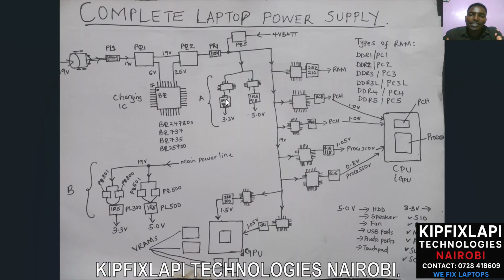Maybe you can go back a little bit here. You can see these inductors. So here, this IC is what steps down that voltage from 19. At this particular side of this IC, we'll have 19 volts. But the output of that IC, from here, we will have 3.3. However, that 3.3 is not yet controlled, so we will have an inductor which regulates that 3.3. By the time we have the actual output of this circuit, which is 3.3, this is now regulated voltage, which is now sent to these components.